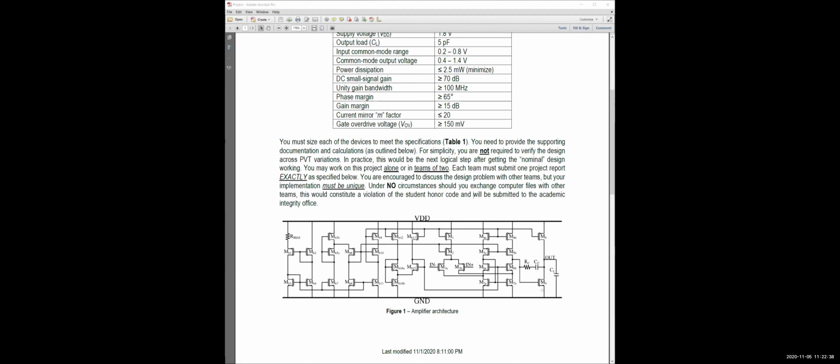I have a question about the circuit. Yeah. So the current bias, doesn't it require a startup circuit to the far left? Good question. It could. Our reference circuit over here may require a startup circuit. Due to its arrangement, it probably won't though. If your design does need one, you can add a startup circuit.